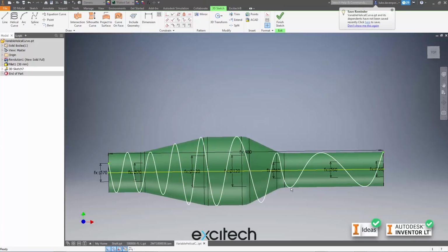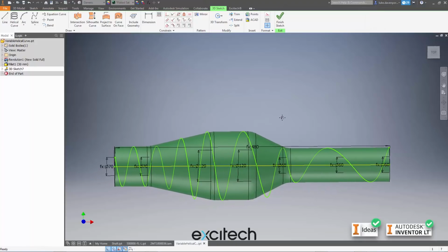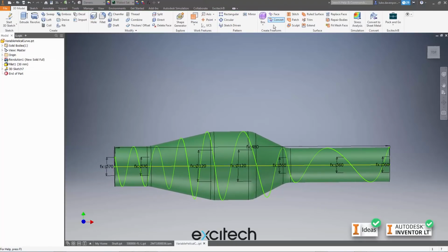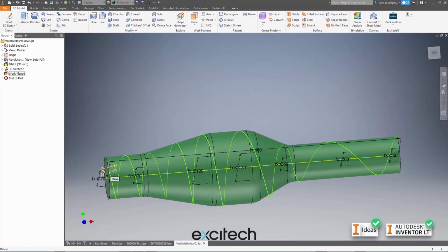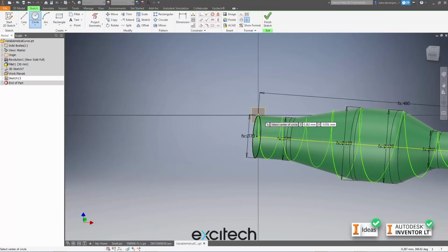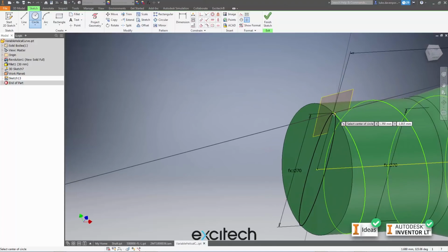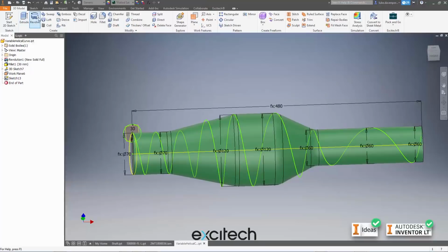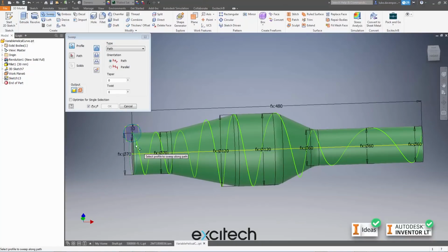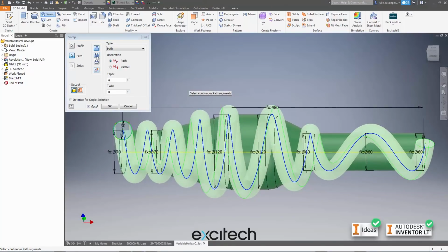If we've got 2 sharp changes here, then we'll see some overlap, and we could use this helical curve now to define a sweep. So that's really nice and easy to do. I could pick there, and I can just sketch on this plane and sweep along a circle, for instance. Let's just sketch a circle of 30 millimeters and sweep that along. Of course, the plane that I sketched this circle in is important, so I'd need to probably adjust the plane that I've sketched it in. And there we go. And I can cut that away, for instance.